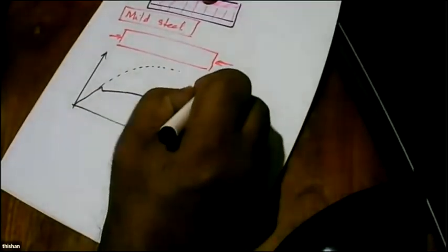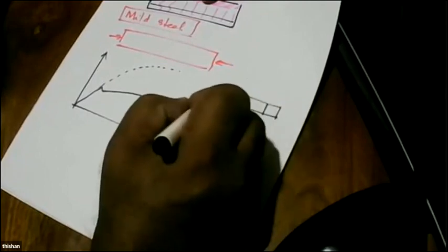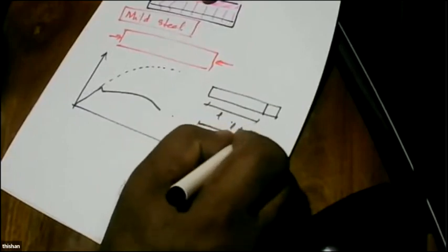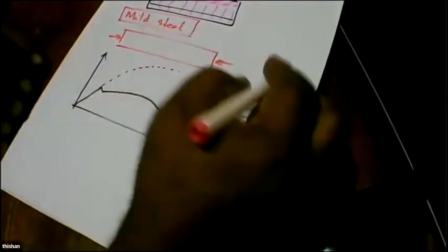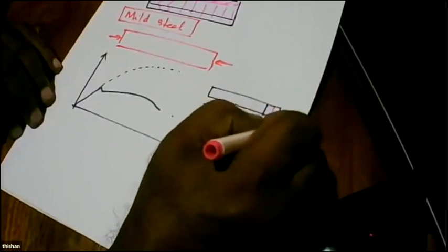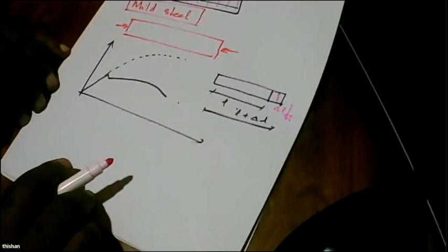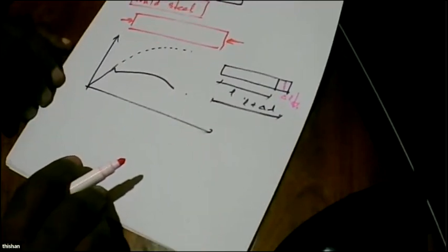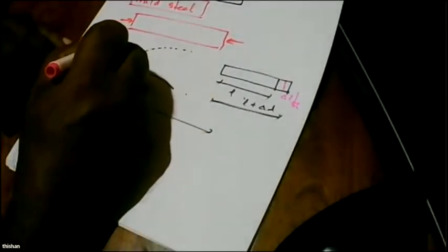So relaxation is, when you stretch steel, this is the original length L. This is L plus delta L. And with time, the steel increases its length, and gradually you find now this delta L becomes smaller. And as the delta L becomes smaller, you are losing the stress. So gradually they developed this, and then they found that they have to go for higher strength materials.